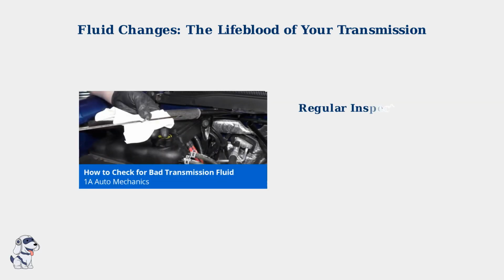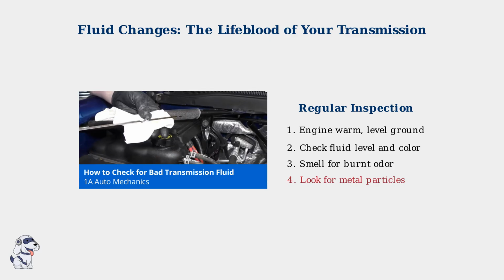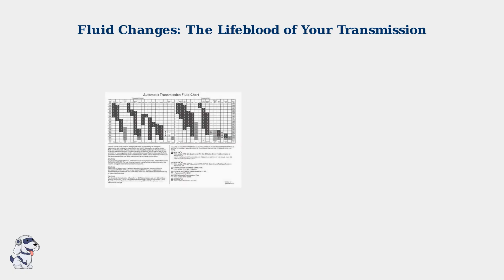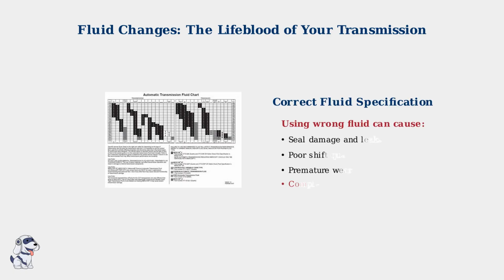Regular inspection of your transmission fluid is simple but crucial. With the engine warm and vehicle on level ground, check both the fluid level and condition. Look for proper color, smell for any burnt odor, and watch for metal particles that indicate internal wear. Using the correct fluid specification is absolutely critical. Each transmission is designed for specific fluid properties. Using the wrong fluid can damage seals, cause poor shifting, accelerate wear, and even lead to complete transmission failure. Always consult your owner's manual.